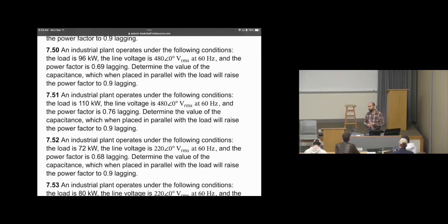Let's go back to the course, 3810. In that course we say there's a power factor, and for power factor correction, basically we need to install a parallel capacitor. That parallel capacitor will work to enhance the power factor. So you will go to your boss and say, we need to purchase a capacitor for power factor correction, which is a capacitor bank, and we will install it there. He'll tell you, okay, take the lead. Come on, tell me which device we need to buy.